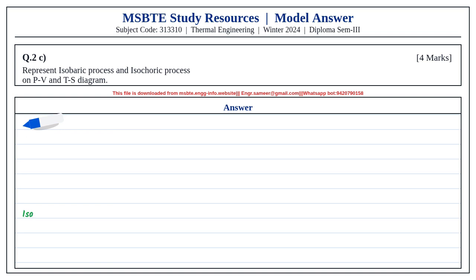Since the given specific volume is greater than Vg, the steam is superheated. For superheated steam, V is equal to RT by P. Therefore, T is equal to PV by R. Substituting values, T is 585 Kelvin or 312 degrees Celsius. Hence, the steam is superheated and the superheated steam temperature is 312 degrees Celsius.